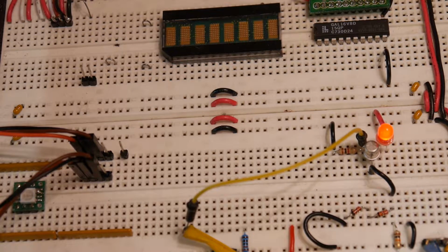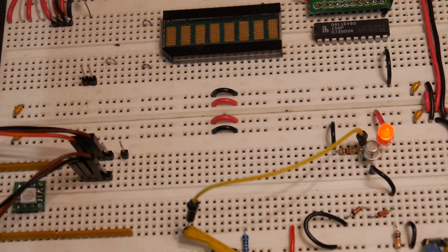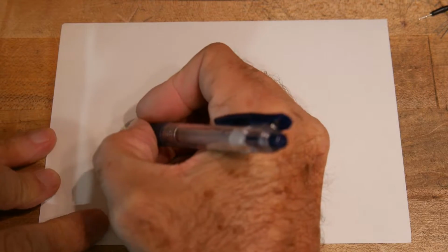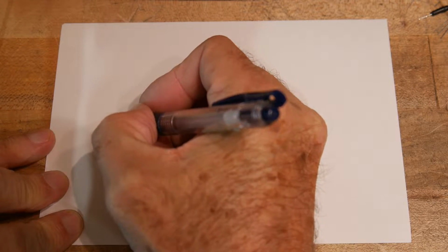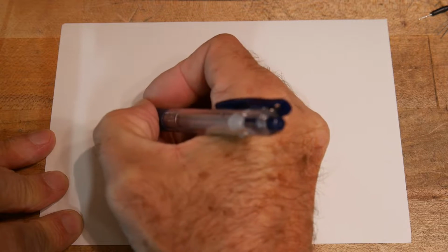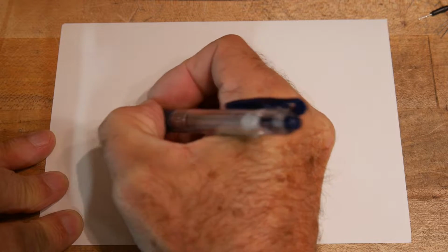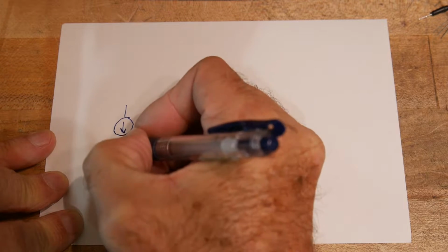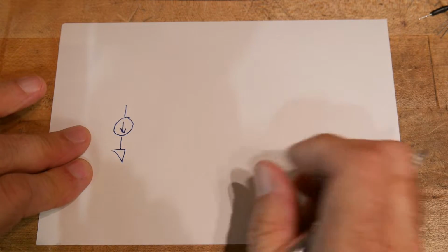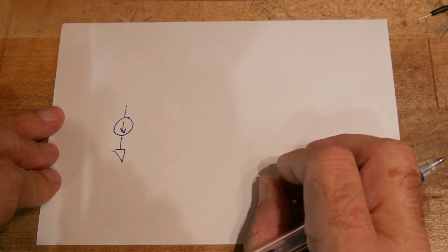They are actually better if you have matched transistors. So inside an IC, all the transistors are matched really well. But in general, transistors are okay. So let's see if we can't build a current mirror. Let me draw a diagram of that. So we have built a current source. So let's say we have a current source. A lot of times current sources are drawn like this. So we have some current source already.